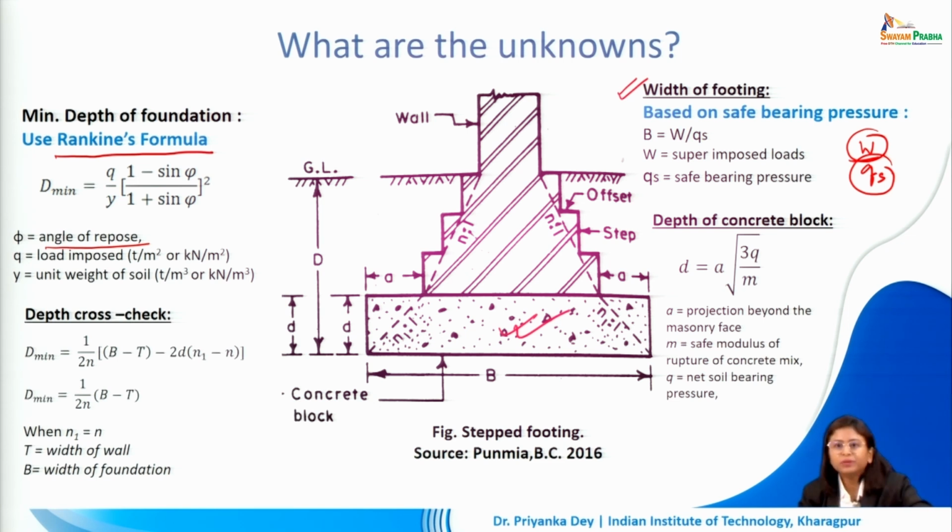This base will be created first within this particular trench. So we need to know what is the depth of this concrete bed so that we can construct this on site, because we already know the width of the footing, we know what capital B will be, but we do not know what small d will be. We have to calculate the same to be able to know what is the concrete base's size.